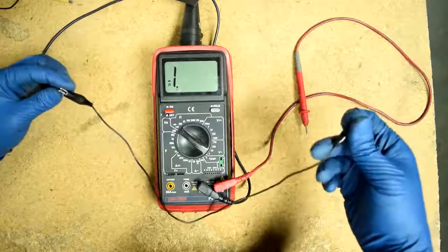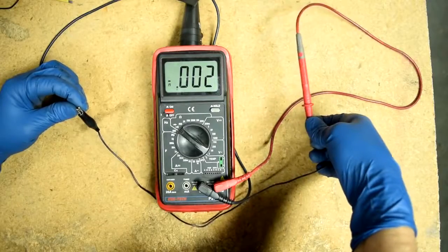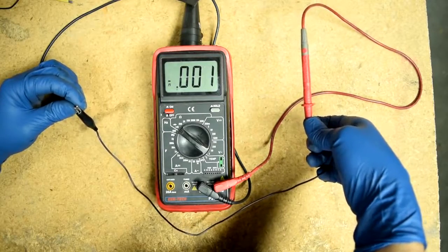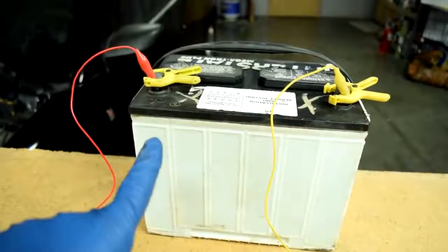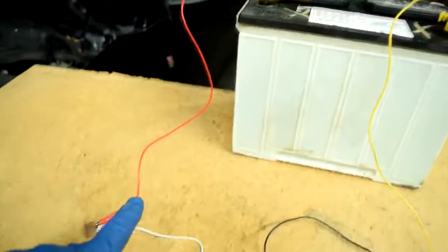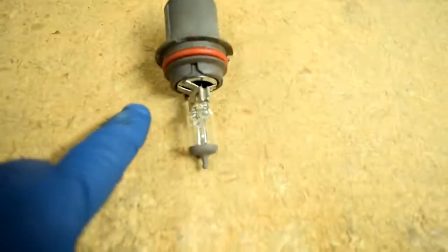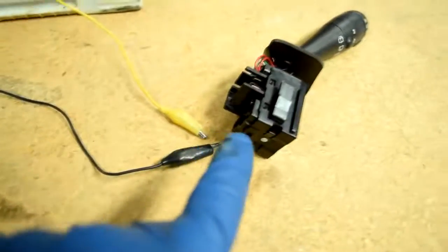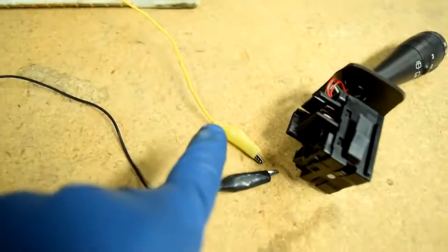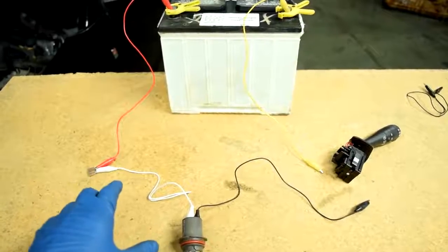So if we were testing this wire with these alligator clips at the end, we would touch the 2 probes, and as you can see, we have continuity as one would expect. So here's a little mock-up of the circuit we have on the board. Here's our battery, there's our positive side, there's the wire to our fuse in the fuse box. From there we got another wire to our headlight bulb, and then here's the ground wire for our light bulb that goes to our headlight switch, and there's the ground wire that connects our switch back to the negative side of our battery.